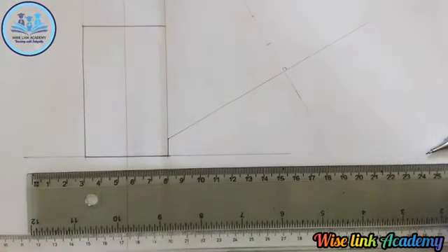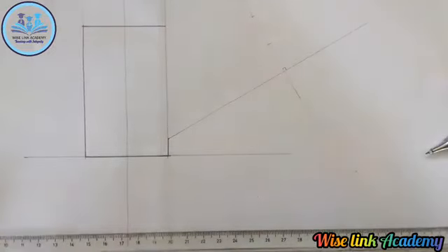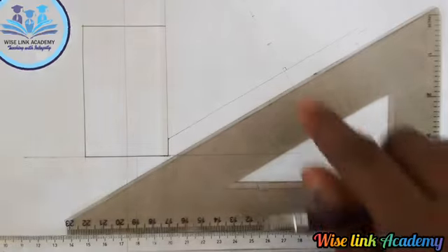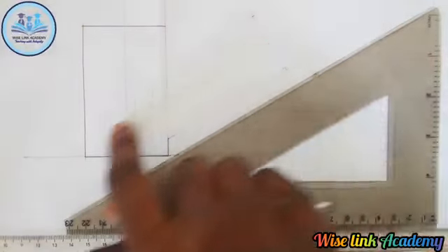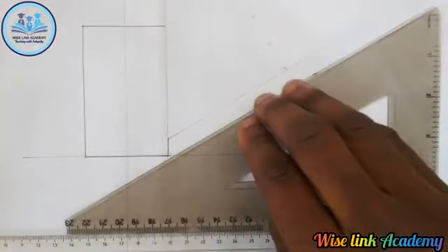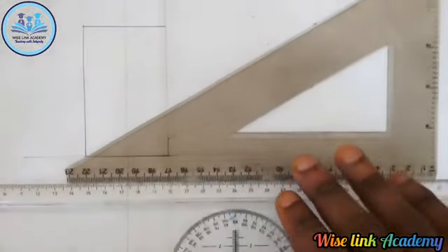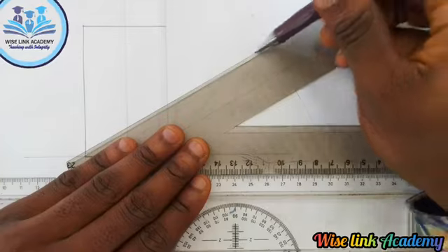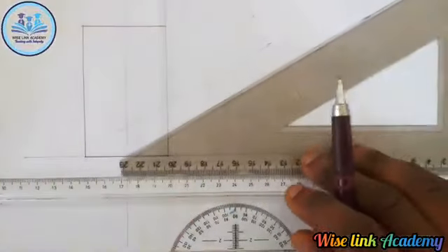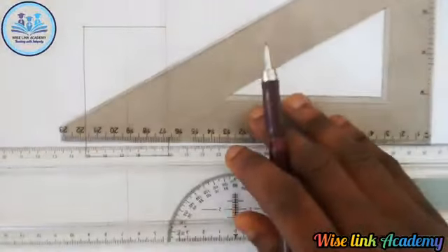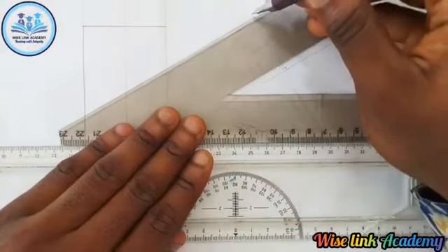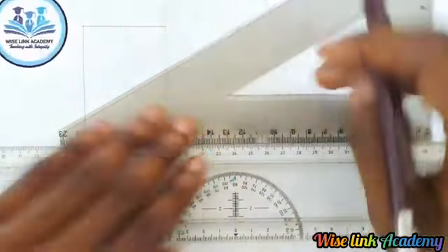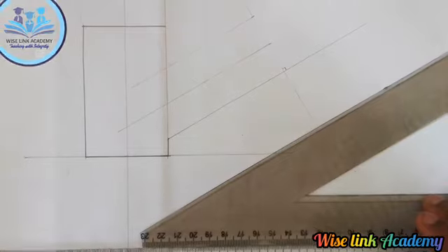So I can just easily take my set square this way. Since I projected with 30, I'll project this with 30 and this with 30. So I have a parallel line. So take it this way. Project here. This is the center point here. 30 this way, as you can see. Come to another point here. Project this point here with 30.